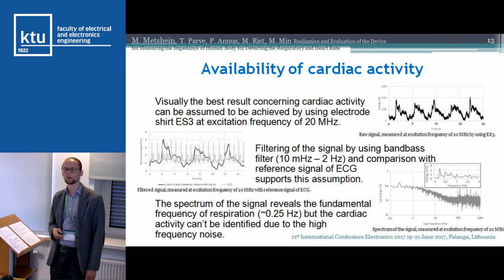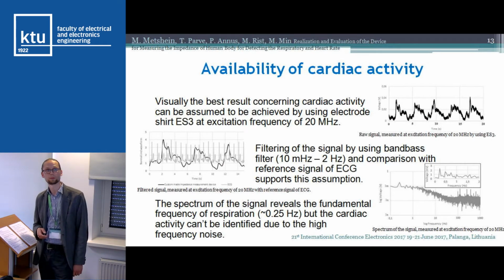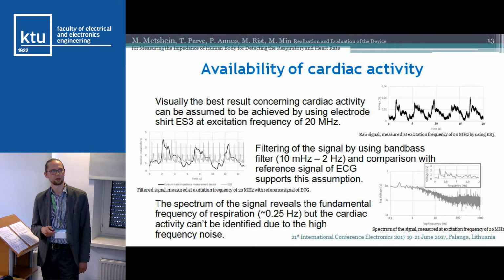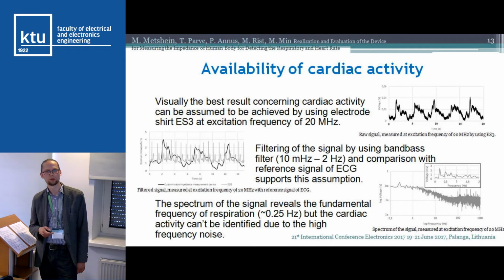Now, concerning the cardiac activity, it can be assumed that the filtering can reveal more data. So here is the raw signal, and now here is the bandpass filtered, post-filtered later in LabVIEW, which reveals a congruously gathered ECG signal.